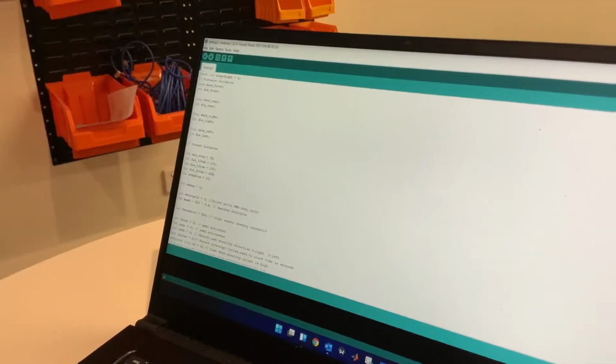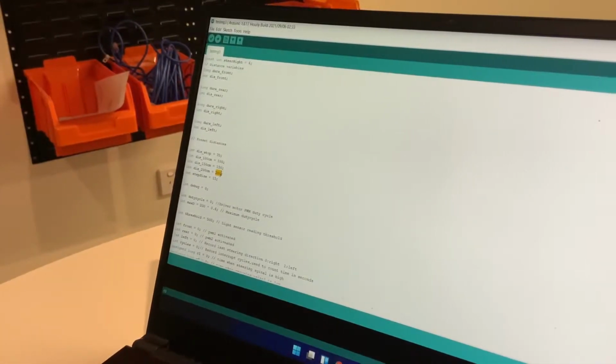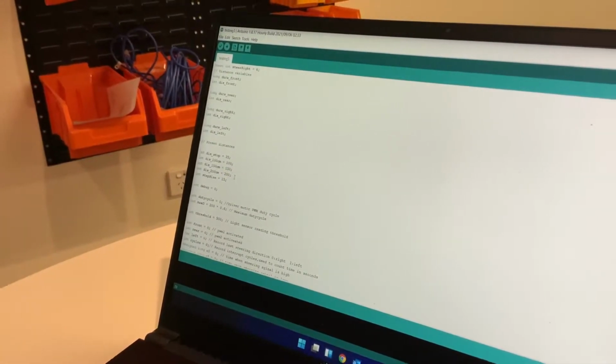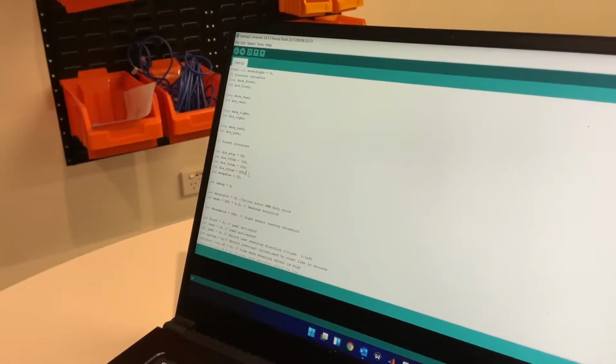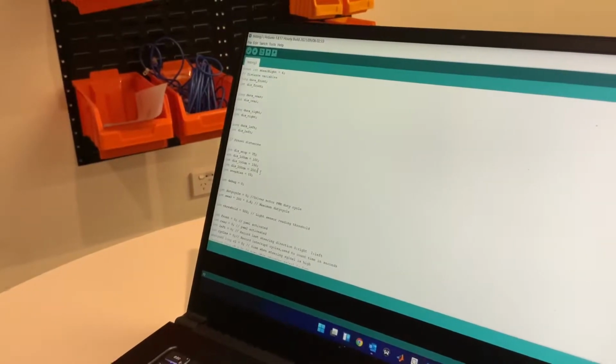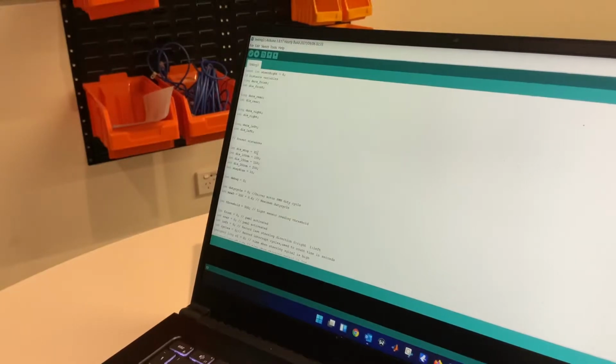We defined 200 centimeters as the distance where our PWM will not be activated. Anything less than that, we have defined our duty cycle to activate, gradually going 75, 50, 25, and then stop when it's less than 35 centimeters.